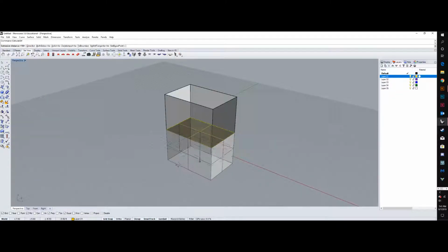It'll use whatever command you've used the most whenever you're searching for commands. Now if I do it in this direction and I type in 10 feet, it still does it in the positive direction because it is a positive. If I do it with a negative, so negative 10 feet, then it will go in the negative direction. Let's get rid of this.